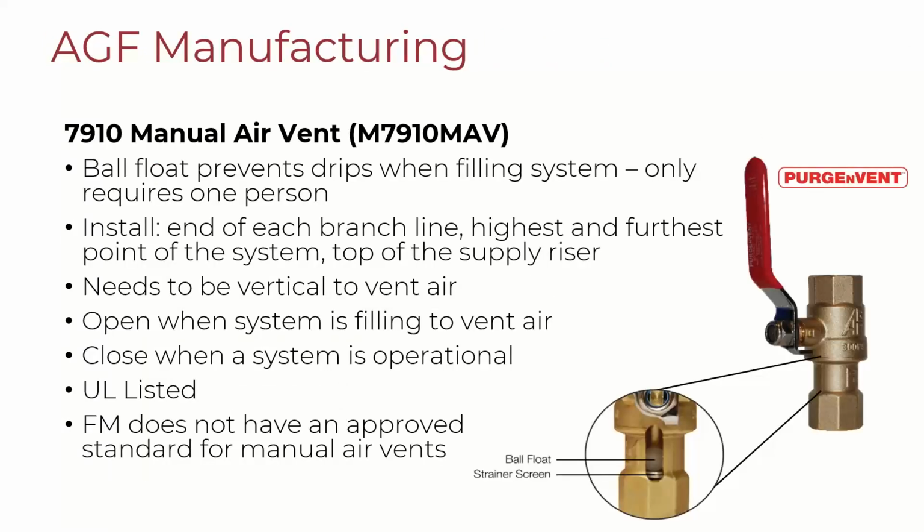AGF does provide a product. We're one of the ones that makes a purpose-built manually operated valve, and it's kind of semi-automatic. It has 2 balls in it. The first is a Teflon float ball that is between the main ball of the valve and a screen strainer to protect it. What happens is when you turn on the water, that Teflon ball achieves buoyancy, floats up into the main ball, and seals itself closed.